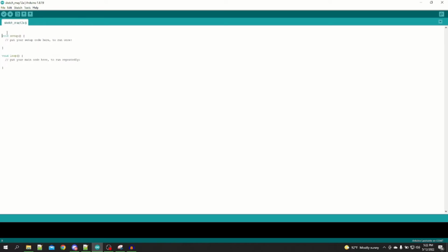The next thing that we need to do is, since we are using a library, we need to make sure that we tell it to use the library. So we have to do these include statements. First thing we're going to do is include any libraries that you're actually going to use. In this case, we're only using one library. So we're going to use the include statement to include the FastLED library, and that instruction is fastled.h. And then we're going to have these define statements here.